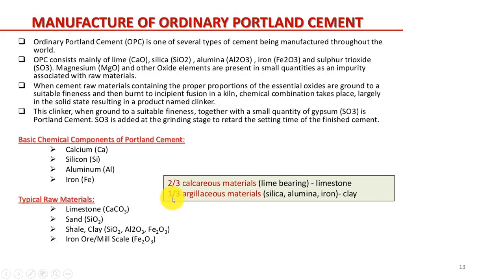Afterwards, the clinker is ground into a finer product. After the clinker is cooled down, the gypsum addition is made depending upon the requirement.